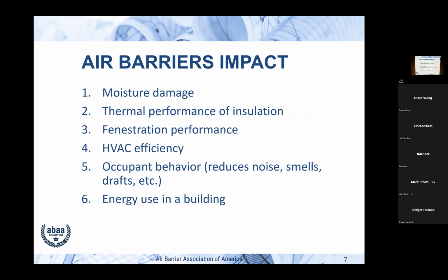So air barriers impact almost everything in the building. We think of it as moisture management and we think of some energy, but a properly sealed building makes almost everything else work better. The mechanical system is going to work better. The mechanical system has a hard time putting air in this room if there's holes all over the place. It's really hard to balance it. I was down maybe a month ago in Los Angeles at the Balancing Association, and my point is you can balance it, but an hour later you're imbalanced because temperatures change, winds change, and all the rest of the stuff.